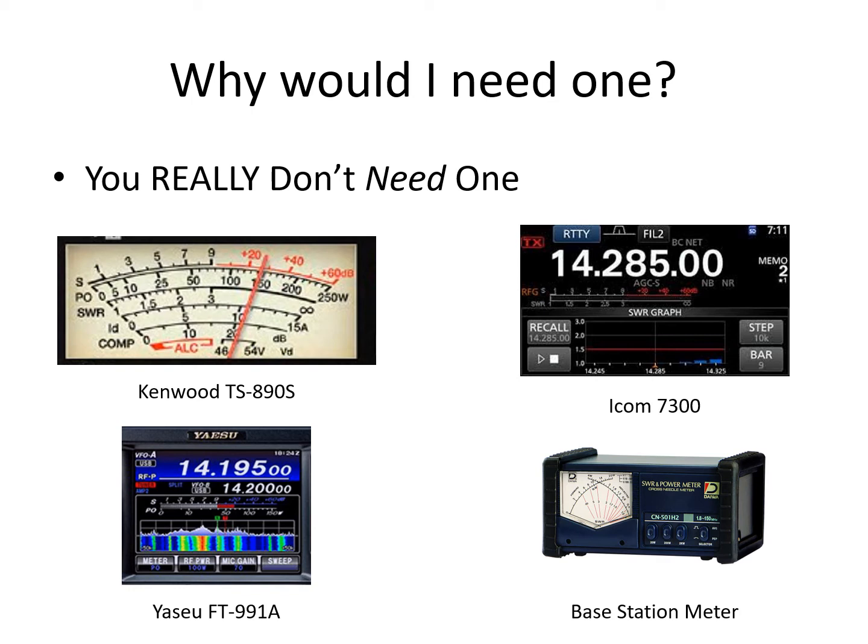is you can use, for example, this is the S meter off the Kenwood TS890S that I have. It's actually a digital display on the flat screen, but it looks like the old analog meter, the S meter, you see even on the older equipment. And you can see there's a scale for SWR, so you can set it up to display the SWR when you're transmitting. So that would be one way to get your SWR readings if you're wanting to adjust the antenna.